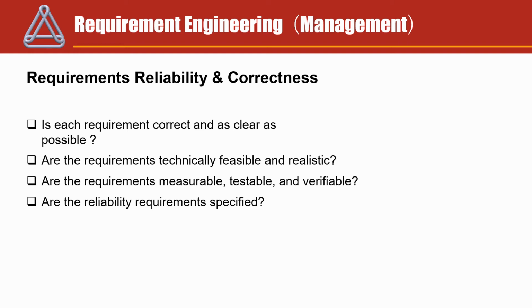Can you measure, test, and verify them? And are they specified in terms of units and values that are achievable? And by reliability, that could be something like, are you going to use the product one time, or are you going to use it 10 times? How many times should it work, or how many times should it cycle before it's expected to need maintenance or replacement?